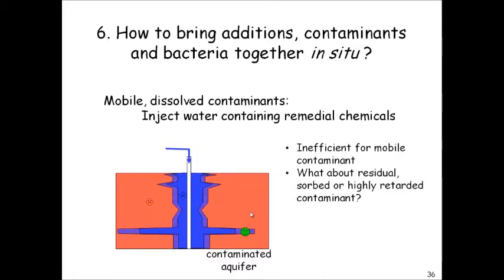Simply injecting water into the subsurface is a rather ineffective way to try to remediate mobile contaminants. We're just pushing the contaminant away from the water we're injecting, and we need those two waters to mix.